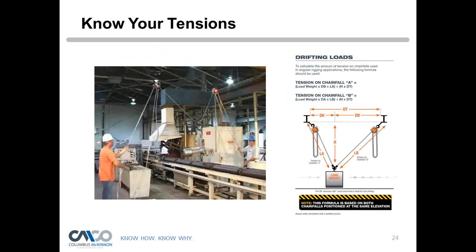And then we have here what's known as load drifting, another way to use hoists at an angle. Here, you wouldn't want to use beam clamps to connect to the top girder, or the picture I showed where you take a sling and wrap it around the I-beam and use sling protection. You certainly want to do that to protect your sling. Again, there's engineered padding and Kevlar, so you want to look into that. The engineered padding is meant to prevent cuts. A lot of people will use steel pipe and cut the pipe so it fits over the flanges of those I-beams. That's pretty good.